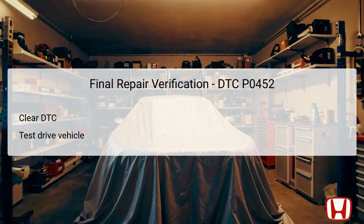After addressing the identified issues, it's crucial to perform a final repair verification to ensure everything is functioning as it should. Begin this process by clearing the diagnostic trouble code, DTC, from the PCM. This can be accomplished using a scan tool capable of resetting error codes.